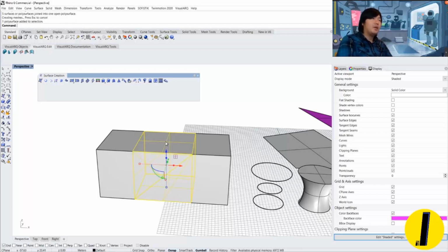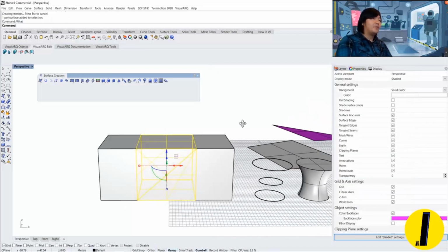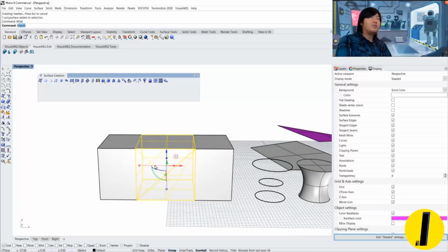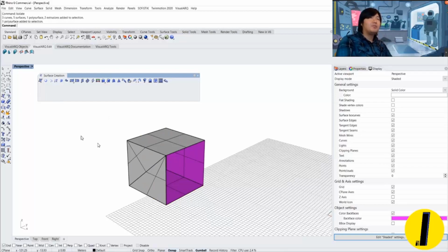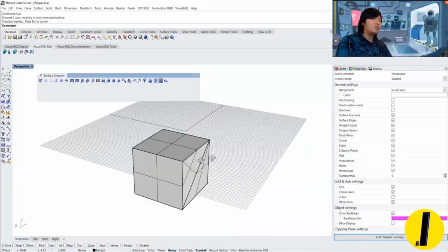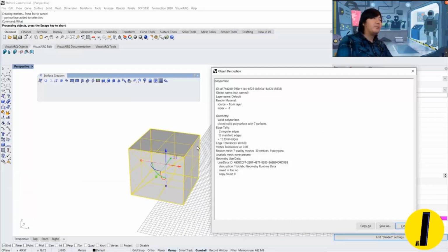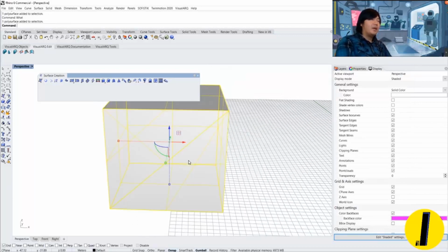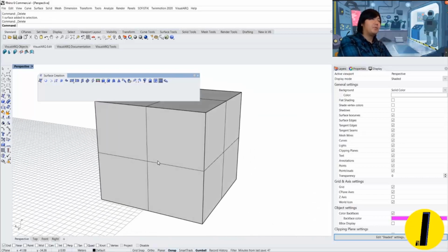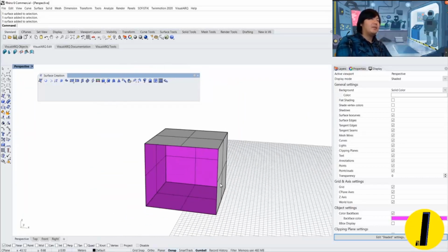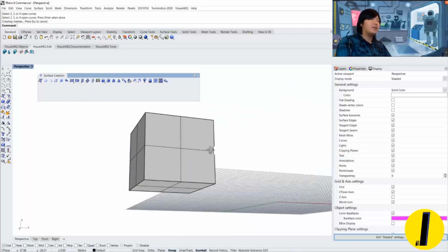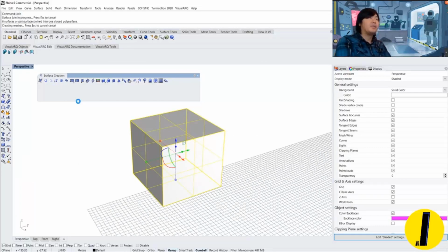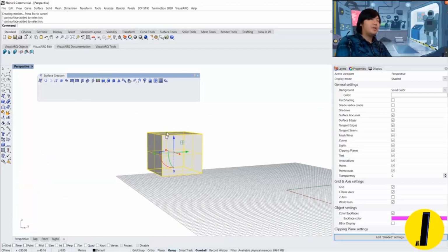Join, same as AutoCAD. So when you join, the surface now becomes a poly surface that you have now joined more than one surface. There is also the command isolate, which is the same as AutoCAD. You isolate the selected object, and you can continue to, for example, now if I type cap, then it encloses the entire surface. So now it becomes a kind of poly surface that is completely enclosed. And you can also use the explode command, or here you can click on explode. That means we could explode the poly surface into single surface objects, and you can delete those two surfaces that you don't need, and we can simply connect them again as a cleaner surface, and I can join them again. Join. So by doing this, we create a complete solid object.